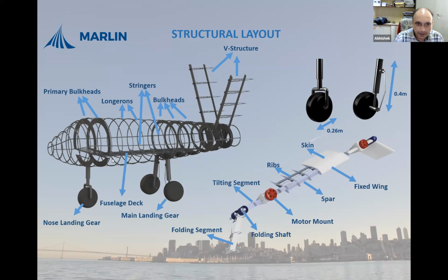This is the breakdown of the whole wing, and again there are ribs. Individual airfoil sections are called ribs. This is a similar thing which is used for aero modeling also, but aero modeling has learned from aerospace, not the other way around. And for your skin, you may have a Nomex honeycomb inside, or you may have different foams. For example, there is a foam whose name I forget. There are aerospace grade foams which can be used inside wings and rotor blades also.